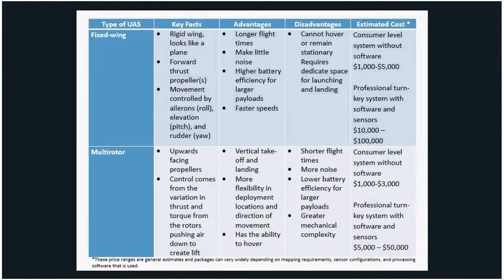And quite often the flight planning is a pretty small program that can run off a low-powered laptop that you want to use in the field, versus something super high-powered that you want back in your lab that does the processing. Yeah, so you typically run the flight off a tablet and the processing on a beefy desktop if you've got it. Yeah.